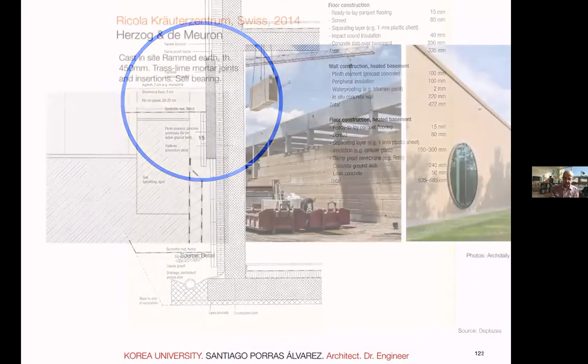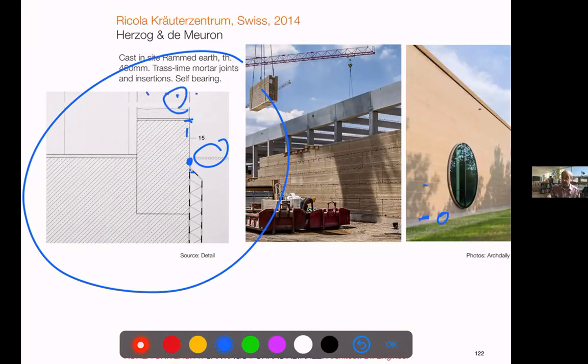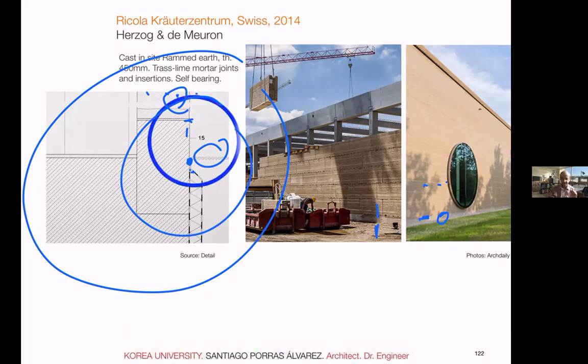This is one example of earth membrane. You see the gravel in the border and the ending of the waterproof just in that point, right? It's already commented. How can you have this border? This is a little part of concrete. You see here, very tiny. And then you have the lime earth, very sensitive against water. So you need to have always this kind of separation to avoid the water eroding that element. This is very minimalistic, but it shows you how we all fight with this very point, right?